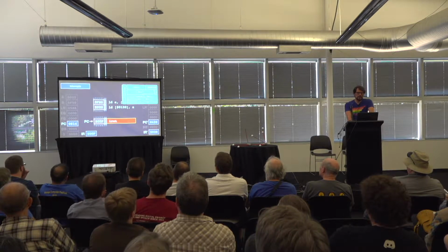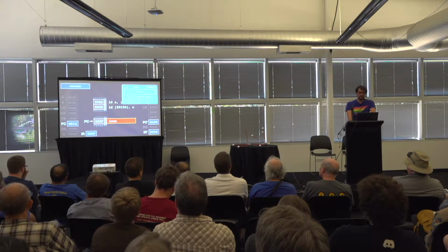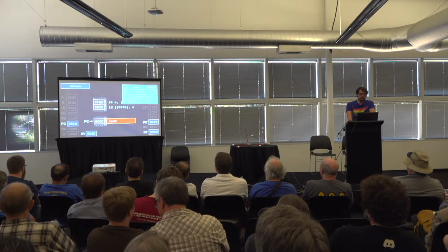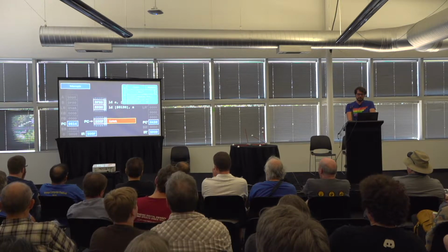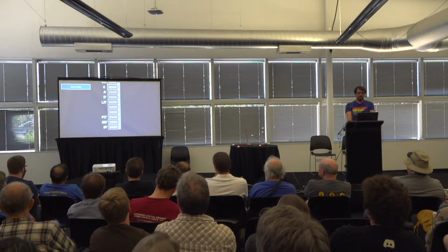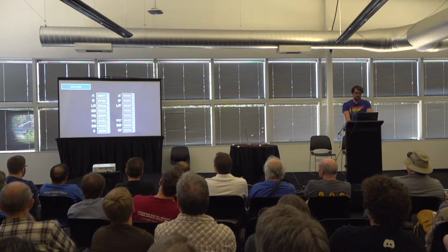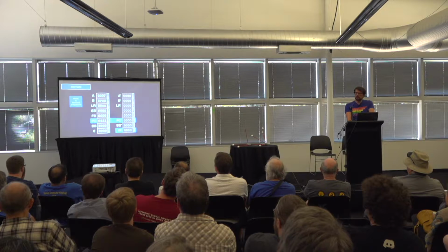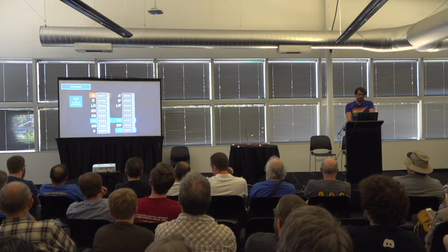When the interrupt handler is finished servicing the device, the IRET instruction will copy PC prime and IR prime back into PC and IR, so execution will continue at the original location. Memory locations 8 through hex F are shadows of the 8 registers. PC and IR are automatically saved by interrupts, and the remaining registers need to be saved by software if necessary. The overflow and condition flags cannot be saved or restored.